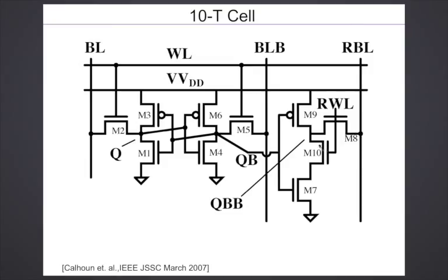In addition, they have put a PMOS, M9. The purpose of PMOS M9 is when QB is 1, that is the case we are concerned about. M7 is turned on, but M10 is off. But they are still concerned, they don't want this node voltage to eventually drift down to 0. So they put M9. M9 is also off because QB is 1, M7 is on, M9 is off.